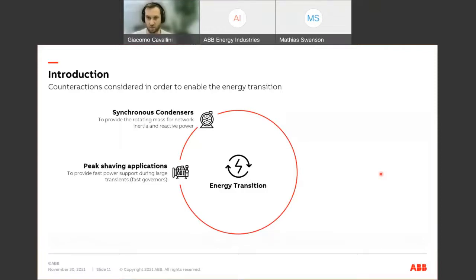So units, small engines, for example, that can start up from 0 to full power in 30 seconds. And those are used, of course, to stabilize the frequency of the grid during certain moments of the day. There is also increased demand for frequency containment reserve, for example, battery systems or supercapacitors that are able to give a very fast contribution.